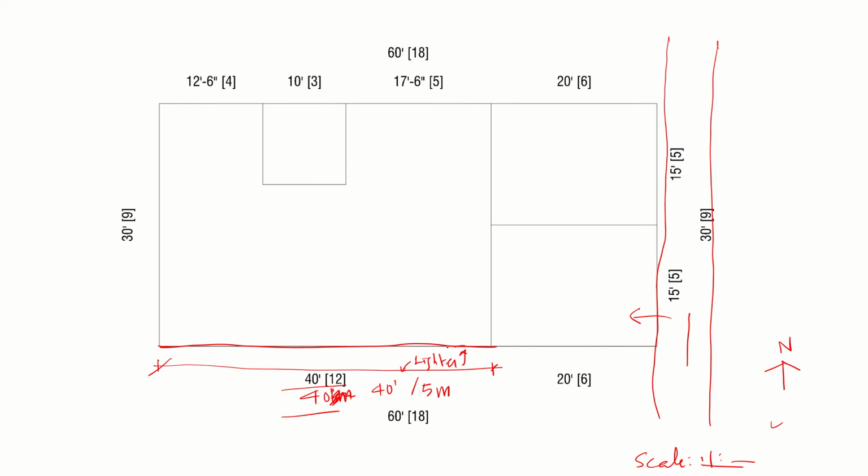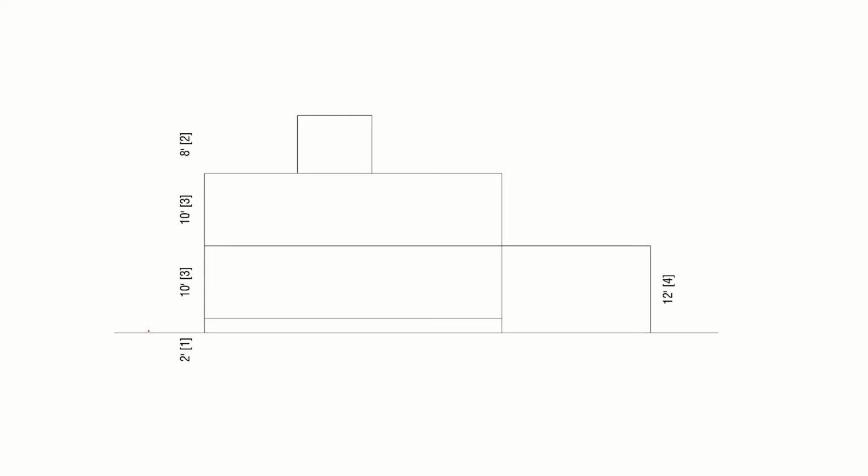One more thing. In the elevation, what I see is nobody is drawing the ground line. I've been repeatedly saying the ground line should be there. That is the thickest line. We need to draw a thick guideline, the ground line. On top of that you can have the elevations that you are trying to do. Fine, that's fair enough.